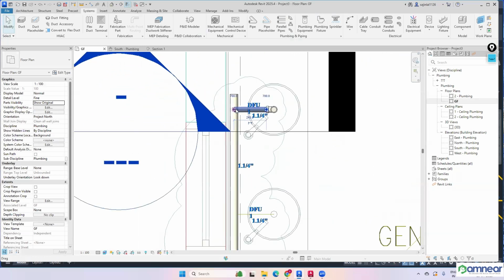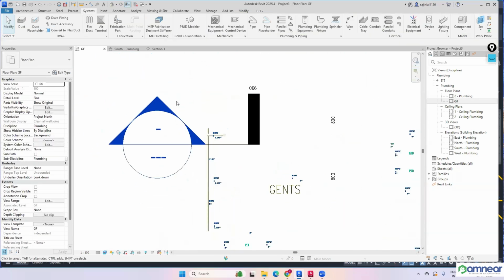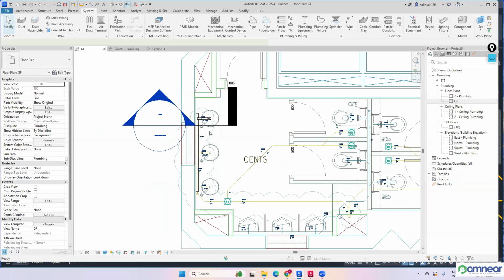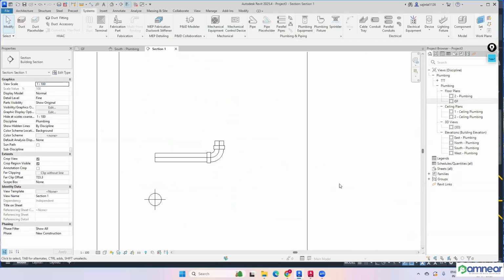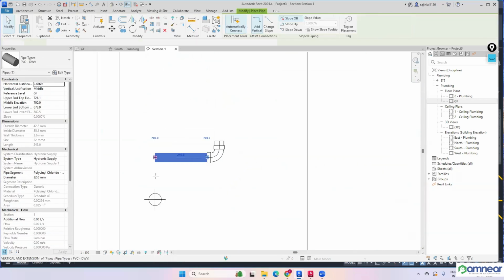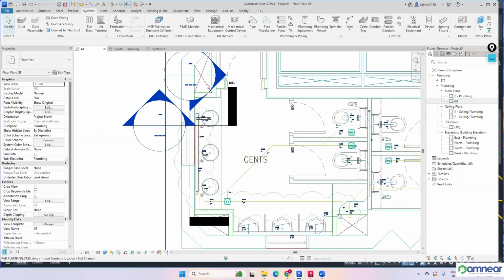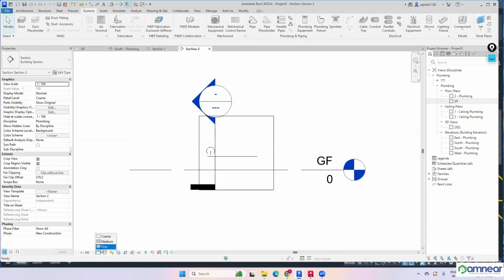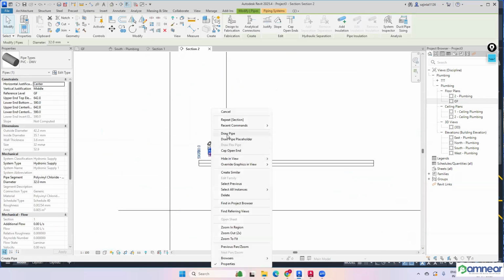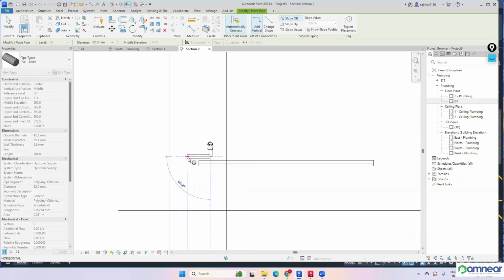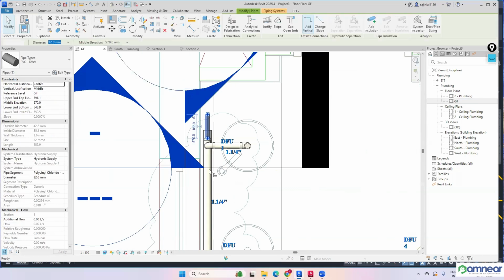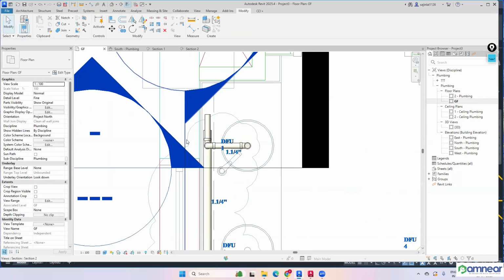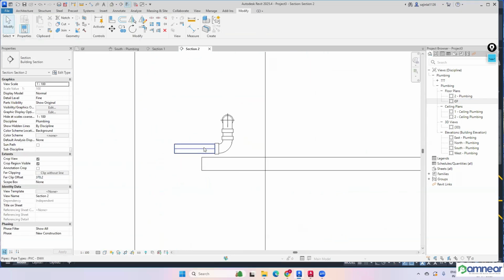And also I need to align the center point of this one before that. Okay, I made a section there. Now I'm making another section as well, because if the center point is not properly aligned, it will be difficult. So I just made a circle, and let me make a reference pipe for the time being. This is just for alignment only. The center line of the pipes has to be aligned, otherwise it will be difficult to place. Now I'm selecting this, align. Okay, now the pipes are perfectly aligned. We can delete it.